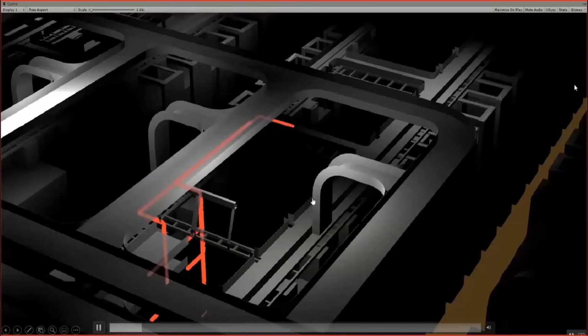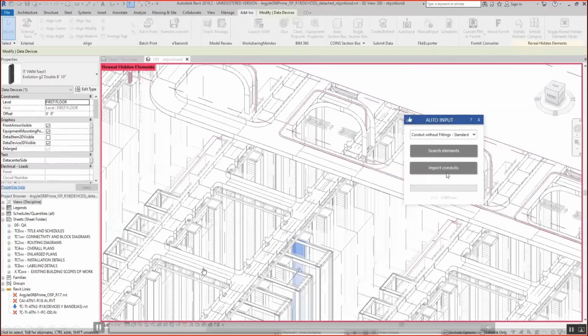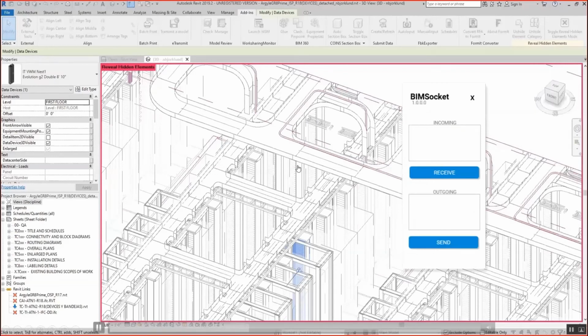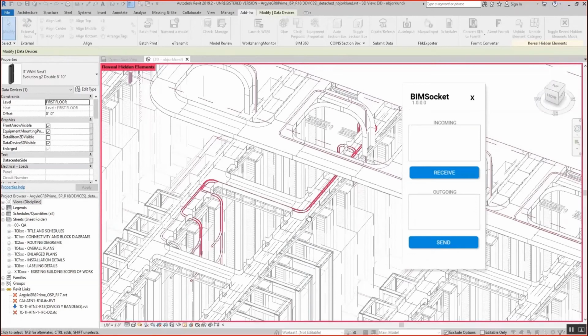As you see, you're looking into a Revit workflow or Unity workflow here, and we are modeling lines through cable trays. We're taking those lines into Revit, and we are modeling those lines into conduits. So there was no need for us to model all those conduits in Unity. We just model lines and then we export it into Revit. So you can decide what you filter.